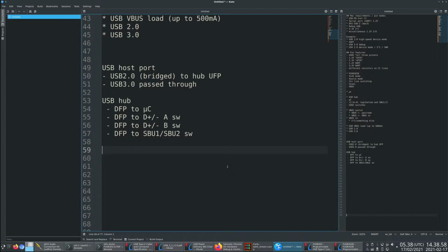Yeah, don't get me started on USB 2 latency constraints over 5 meters, because I have a VR headset that has a 6 meter USB 2 cable, and it only works with half of the PHYs on the other end, because HP were lazy about putting redrivers on both ends. So yeah, I have to run it through a hub to make it work. But we're not going to use long cables for this. This is a test device, so we're not going for compliance with any particular standard so much as general usefulness with short cables and stuff like that.